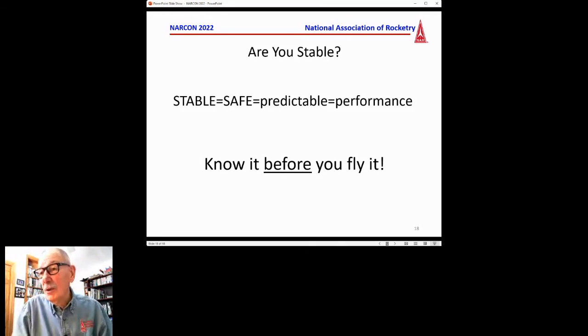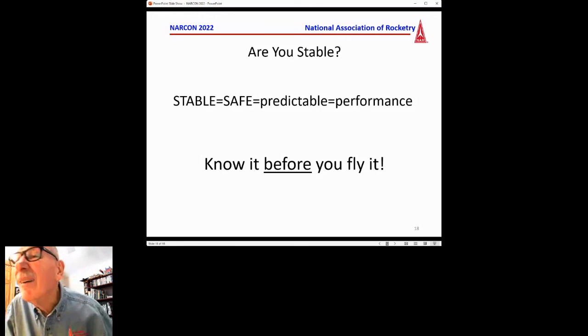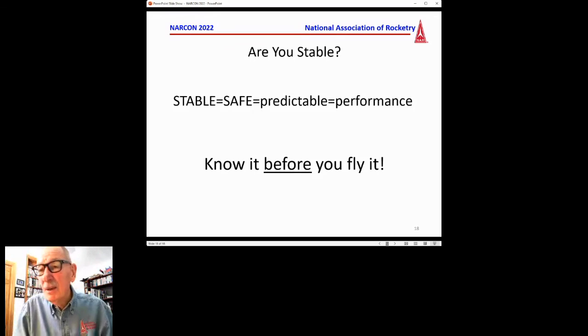The graphs of TR33 are simply the equations put out in graph form. I guess I'm not sure what it was about the graphs you didn't understand, Robin. The idea was that you're able to use the information about the shape of the rocket, either the nose cone shape or the fin shapes, coupled with those graphs in order to determine your center of pressure.